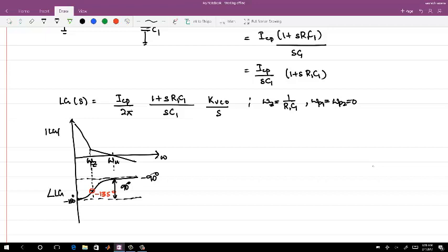First thing is, it is not regarding the voltage domain itself. The transfer function of the VCO is acting as an integrator, right? That is converting the frequency information to the phase information. But where do you get the frequency information? For that, if you recollect, we need one integrator, because we need to integrate the phase error to get a certain frequency error information.